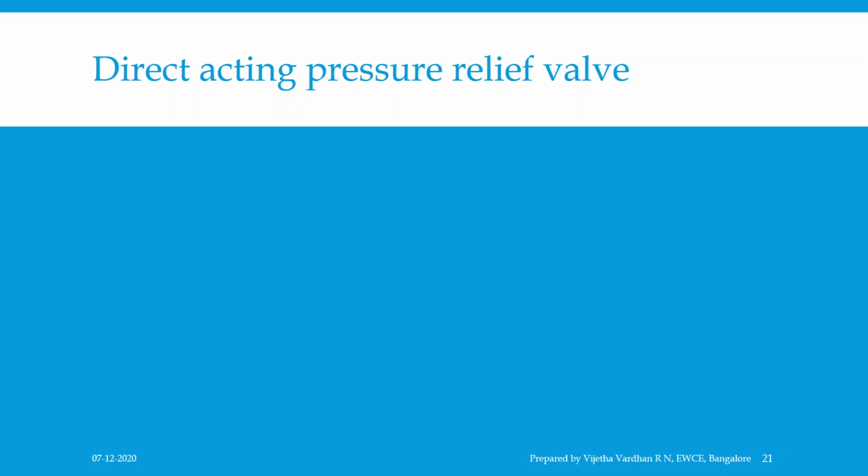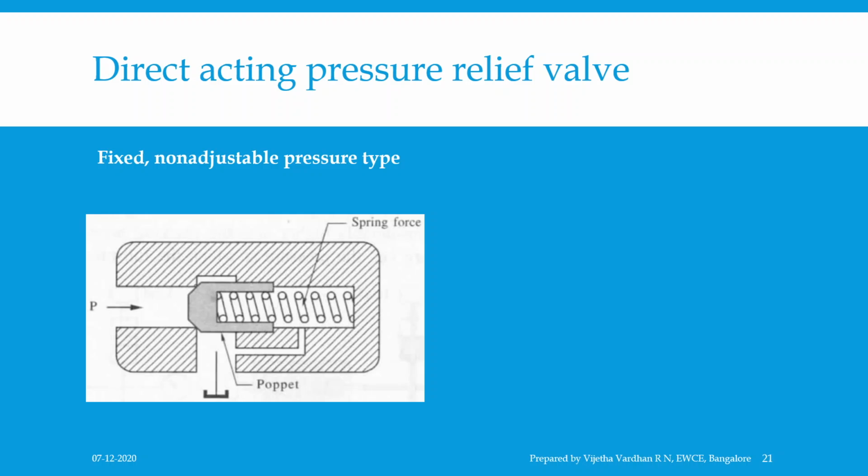The amount of opening of the poppet depends on the differences in pressure between the fluid pressure and the spring pressure. And this direct acting pressure relief valve is again subclassified as fixed as well as adjustable pressure type. Now we will discuss both of them.